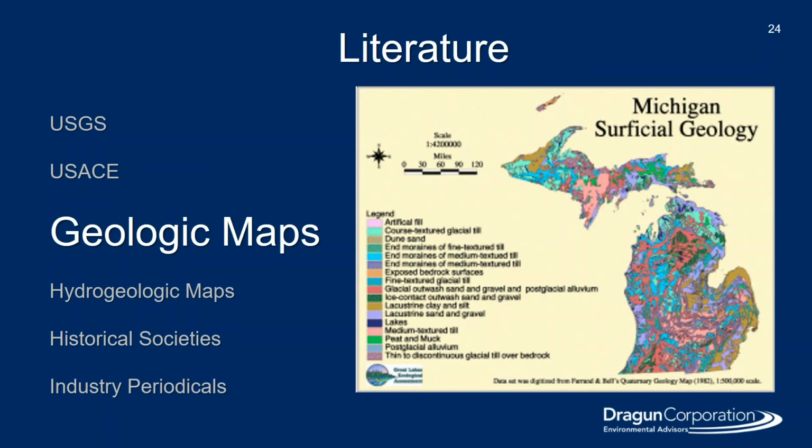Additionally, I mentioned previously that overlying your site onto geologic maps can give you a good kind of peek at the future relative to what you might encounter in the subsurface drilling. We had a site that was very well mapped in the literature and showed a sharp geologic glacial moraine boundary. On our site, we could pump groundwater all day, yet just 200 feet west of our property, people couldn't get groundwater at 200 feet below grade.